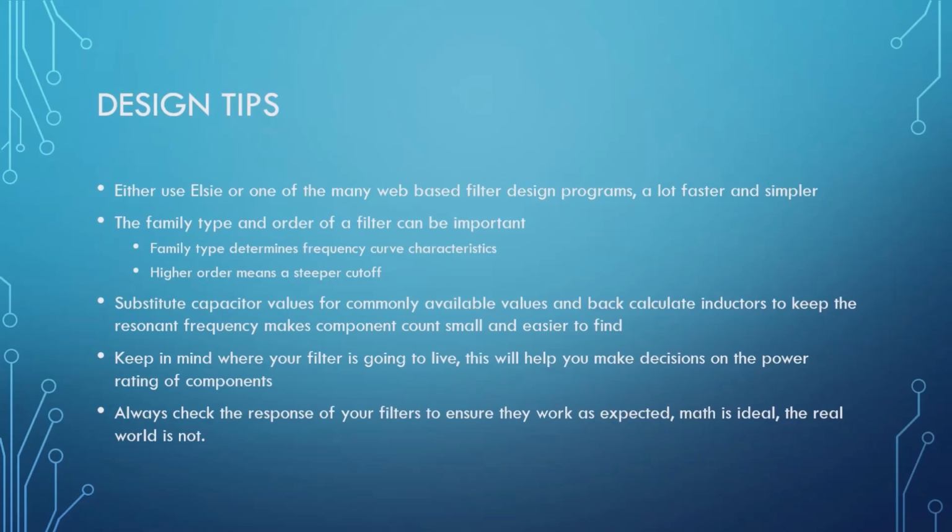We've been talking about a project where we would build a bandpass filter that could take the Morse code portion of a band and separate it, making a filter for that portion and a portion for the sideband side of a band. So we'd probably want a higher order filter so that we get a steeper cutoff, so that we don't interfere with somebody that's working CW versus somebody that's doing sideband on the same band.